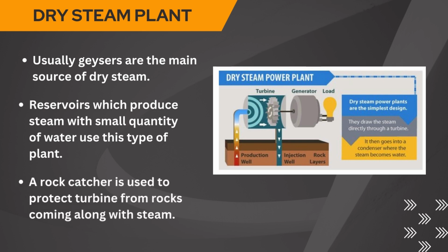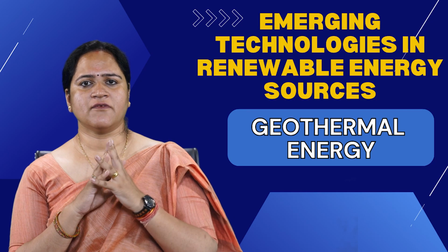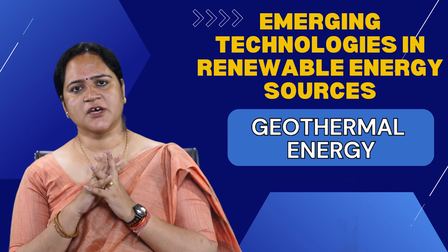Now several rocks may come with the steam or with the water. To protect the turbine from these rocks, we generally use a rock catcher, and this rock catcher traps the rocks that are coming along with the steam, so they will not go to the turbine. From this we can protect the blades of the turbine.